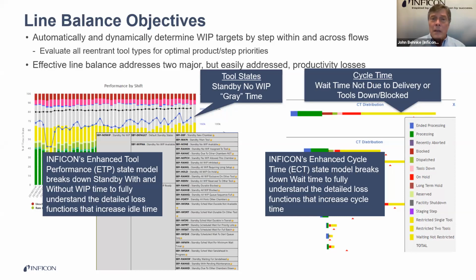The reason that a linear line helps is that if you have a linear distribution of inventory, the WIP is not piled up in one location, so the actual median utilization rate of an entire factory can go up anywhere between 3 and 11%, 15% would be a high case if you're pretty nonlinear. But that's a tremendous amount of free capacity.